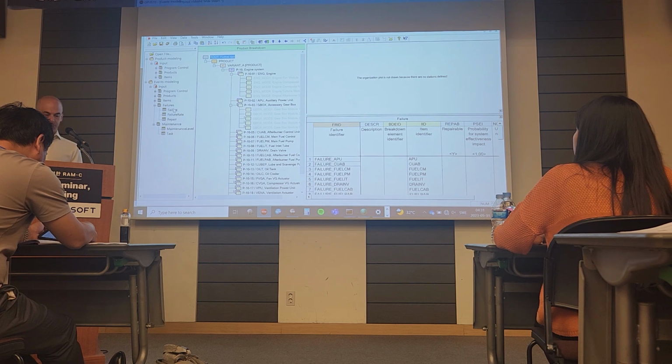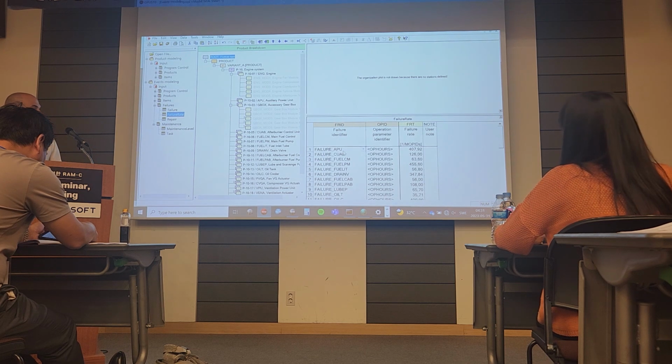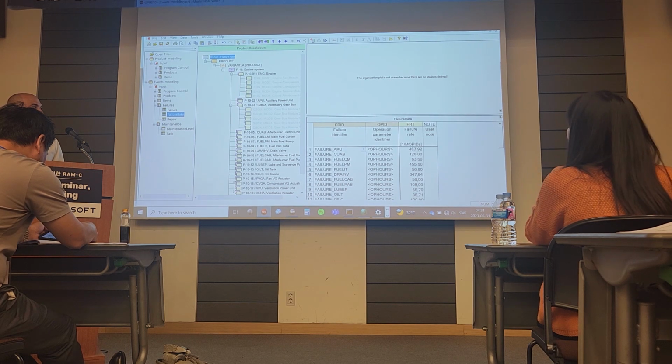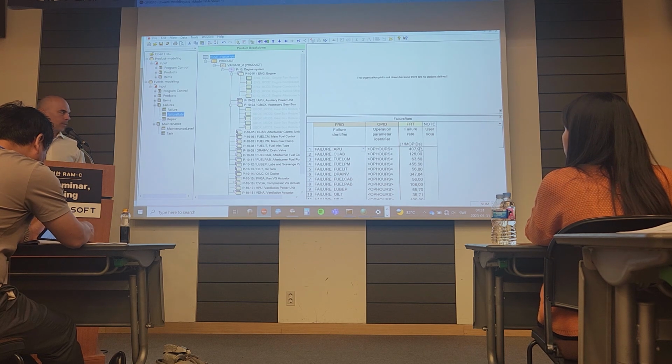And to the failure, of course, we need to have a frequency. So the failure APU has the frequency of 407 occurrences per million operating hours. So in this case, we have operating hours. That means that during 1 million operating hours, this failure will occur 407 times. And why do we use 1 million? This is from a convenience perspective.